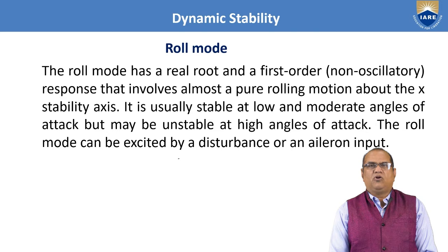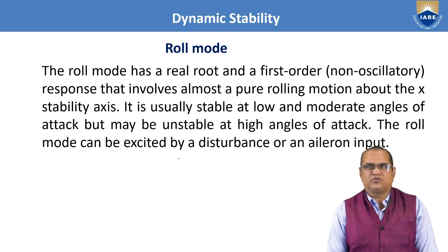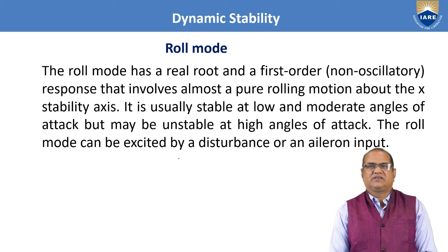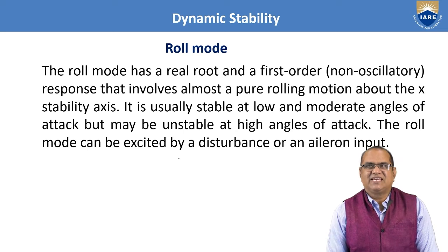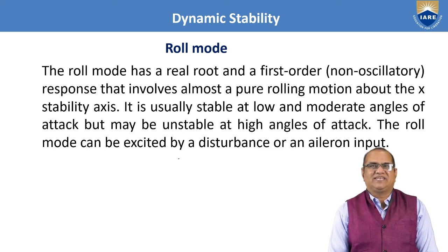The roll mode has a real root and a first order non-acceleratory response that involves almost a pure rolling motion about the x stability axis.